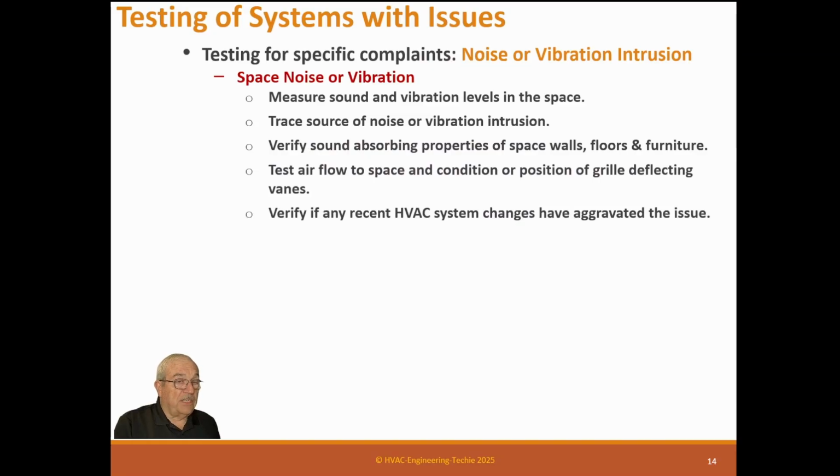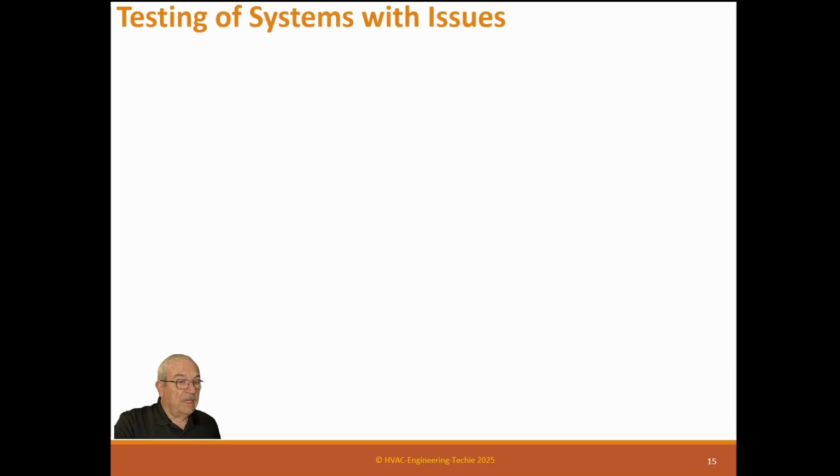Verify if any recent HVAC changes have happened. So did this get worse when they made a change? Sometimes you can find out they did things wrong or incorrectly, or put a different size piece of equipment in, which aggravates these issues. Investigate sound dampening materials and vibration isolation.